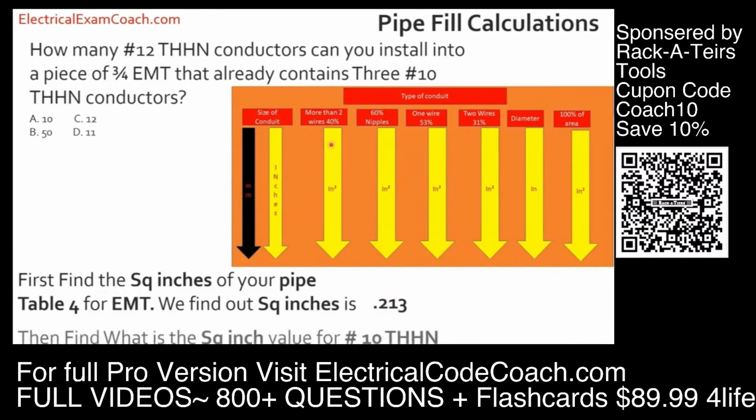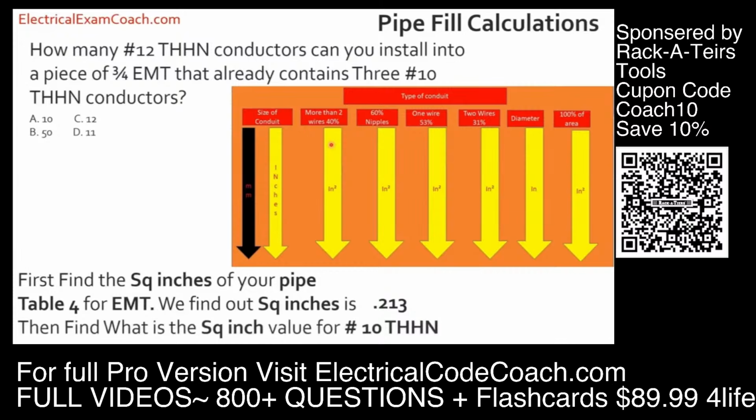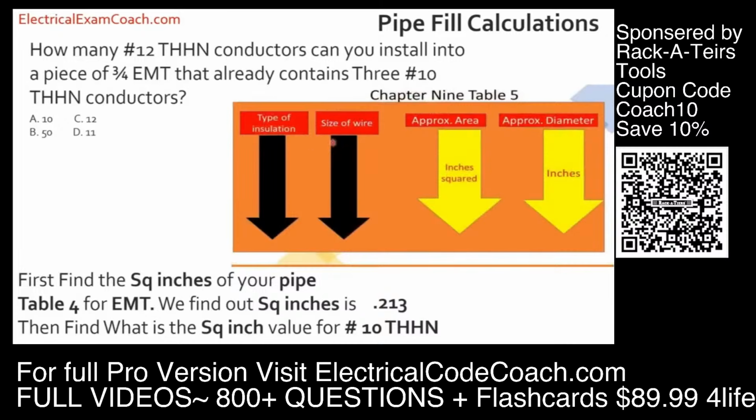Now we need to find what we already have, which is the number 10s. We're going to head over to Chapter 9, Table 5. When we get there, we start on the left-hand side and find our type of insulation. We cross over and find our size of wire. Then once we find that, we cross over to the approximate area, and each individual number 10 is 0.0211 square inches.